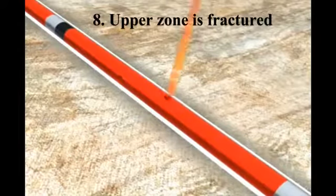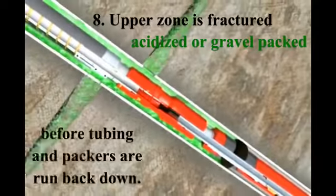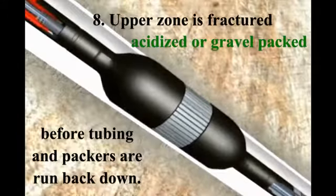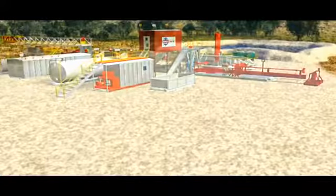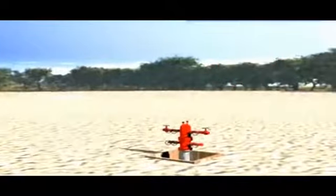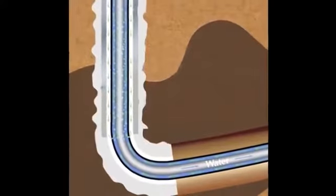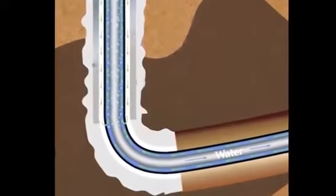Finally, the upper zone is fractured, acidized, or gravel packed before the tubing and packers are run back down. The Christmas tree is reinstalled and the well is brought back to production. To unload the kill fluid, it might be necessary to pump liquid nitrogen down a string of coiled tubing run inside the production tubing.